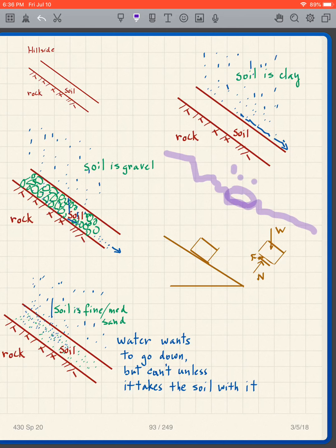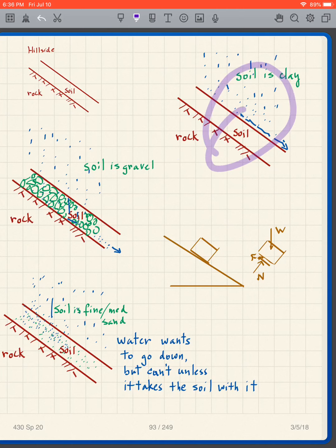We get ponding in various places, and it sits there, and it may dry out, and then we have another rainstorm, and maybe after about 10 rainstorms, what happens? The water sits there, and then it eventually seeps through. It sits in our puddles, for instance, and it seeps into that clay after an amount of time, and the clay can become saturated. So after many rains, the clay can become saturated, and we can have the same problem with the clay.